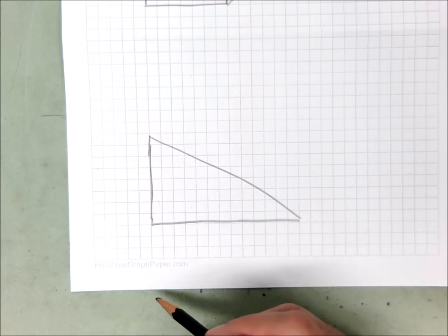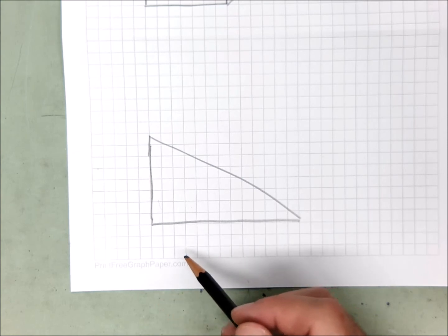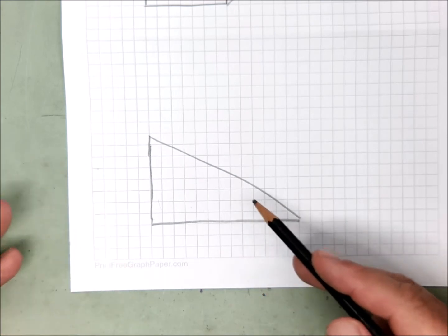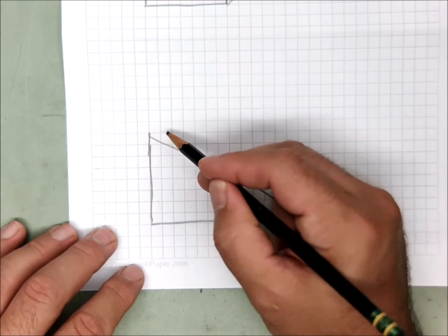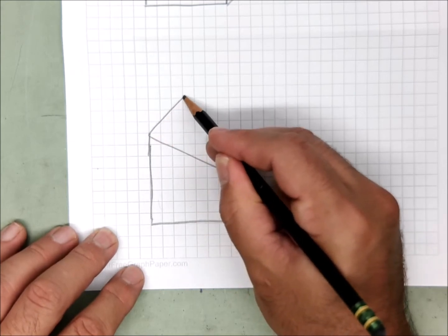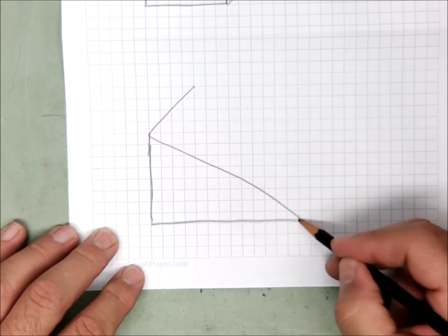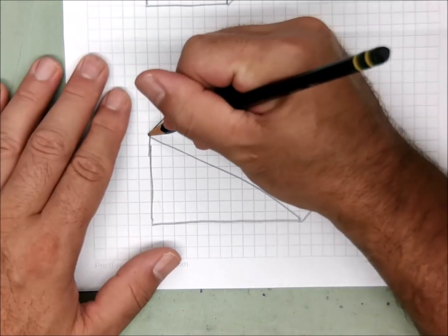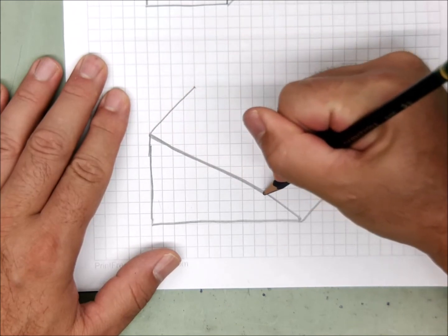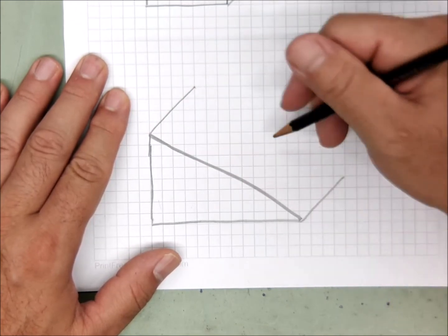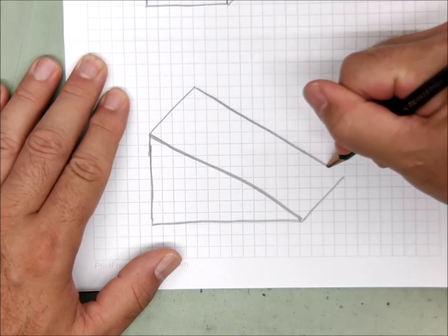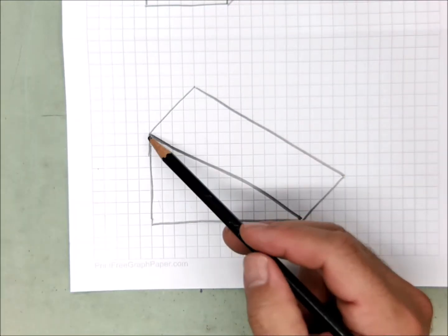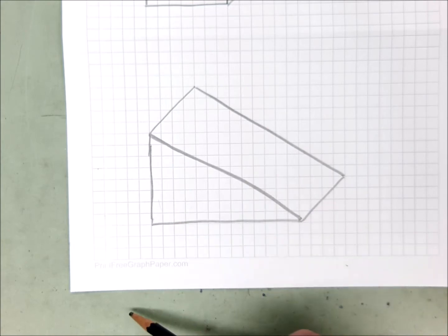So how do I make this oblique? Well, you know, there's really no difference between obliquing a rectangular object or rectangular prism and obliquing something with a slope. Go to the point where you're starting and go back 1, 2, 3, 4. And then go down to the corner here and go back 1, 2, 3, 4. Okay, and here's our diagonal line that makes the slope. So whatever happened in the front has to happen in the back also. Okay, connect the dots. This is what our little wedge or our little ramp would look like if we were drawing it in oblique.